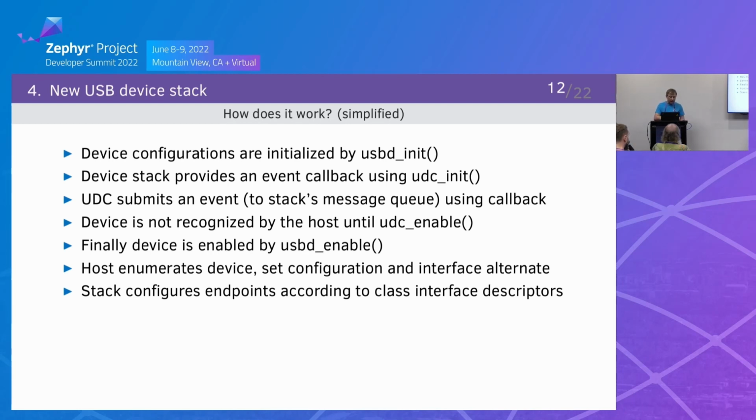The device stack provides an event callback that is used by UDC init in the lower layer, and the UDC driver submits an event using that callback. It's common for all the drivers. As I said, the device will not be recognized by the host until UDC enable is called. Finally, the host enumerates the device, selects the configuration and interface alternatives, and the stack also configures endpoints according to the class interface descriptors.